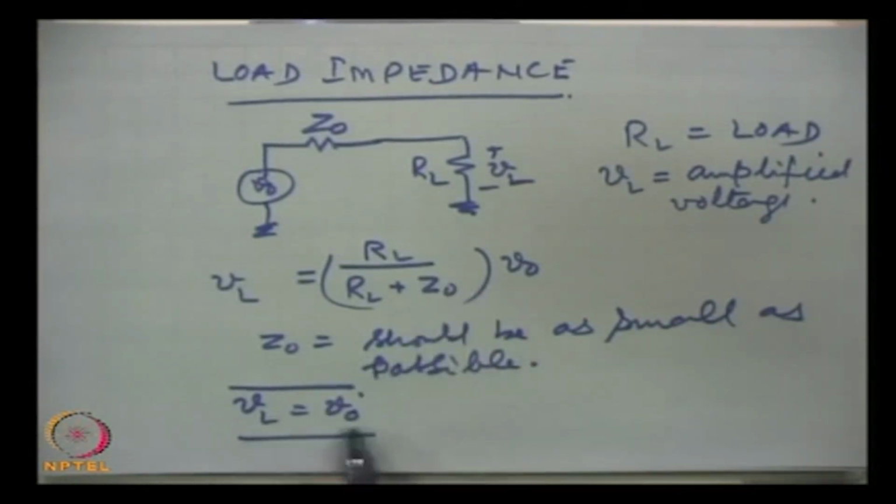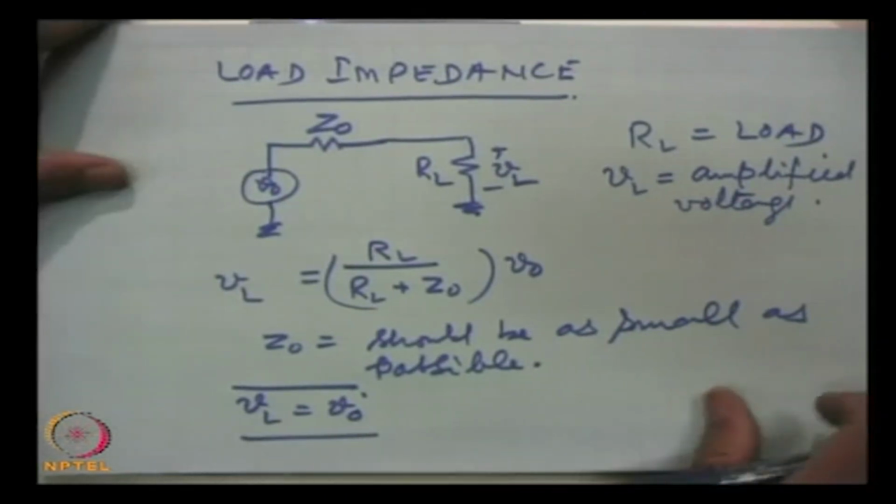When this is low, there is no loss of voltage. So, remember that the source which we use with the amplifier, its impedance RS should be low, and the output impedance of the amplifier should also be low if we want proper voltage at the load. Now, we come to R parameter analysis.